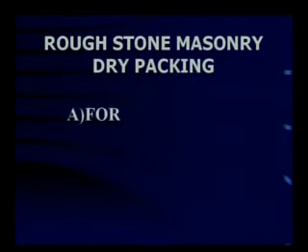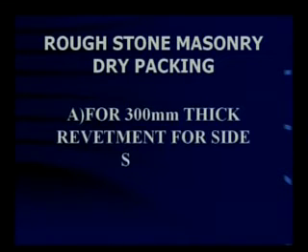Shall we move on? Yes, it is rough stone masonry dry packing. The first item, as I have told you, is the 300 mm thick revetment for side slopes. Why do we need a revetment? We need a revetment as a protecting layer, a blanket of stones, so that the slopes do not slide away. To protect them, we need a revetment.